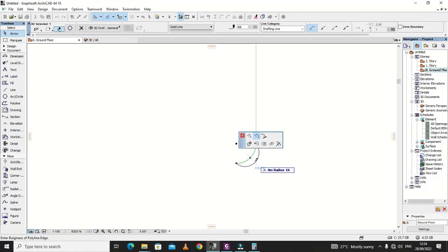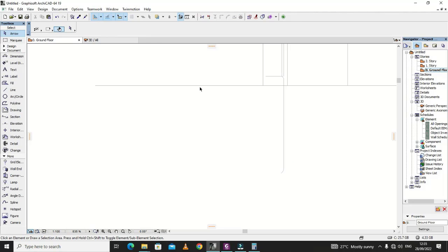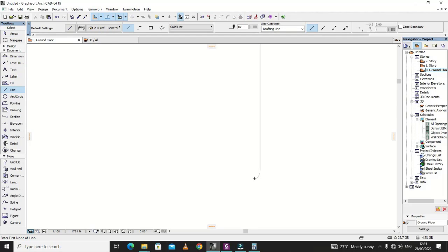You can make this a little bit bigger, like that, so that just shows the bar was a little bit bent. So this is the development length, so that one will be calculated on site. So this is for the starter bar, and we have already drawn that part of the drawing.